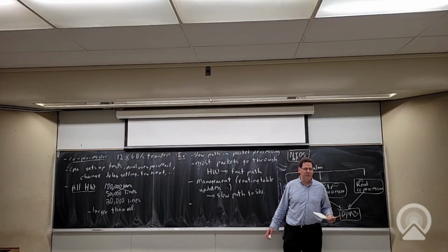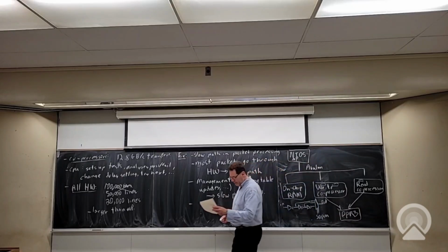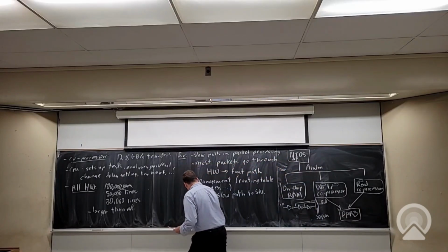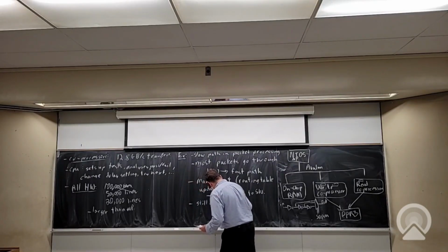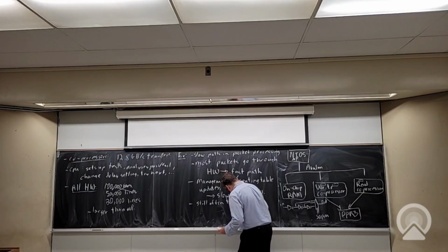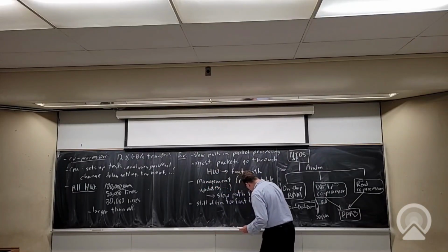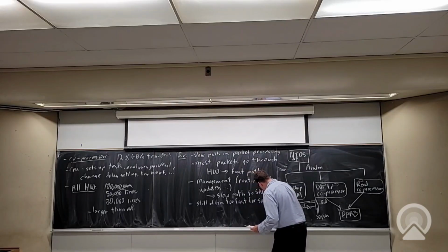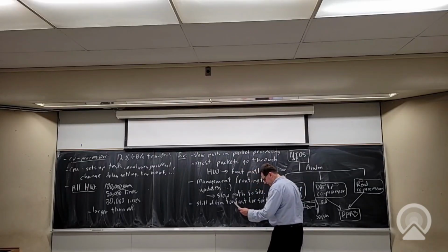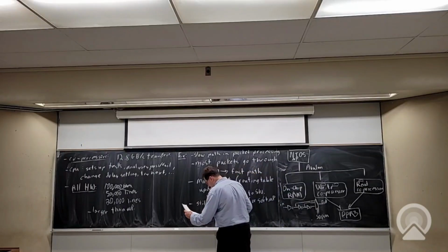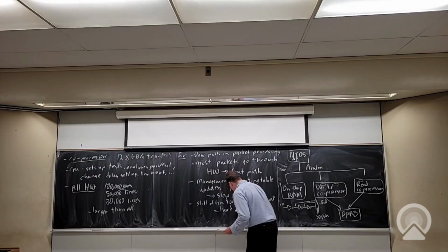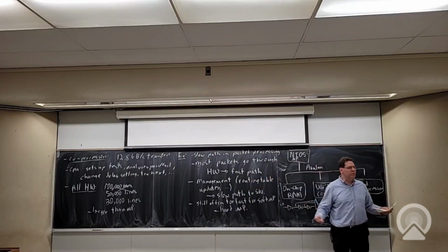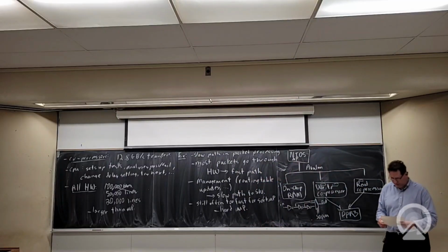Even if only 1% of packets go through it, it can still be a fair amount of processing. So this is still often too fast for a soft processor. So this is basically one of the arguments for a hard microprocessor. Not the only argument, but it'd be a use case where having a faster microprocessor available is useful.